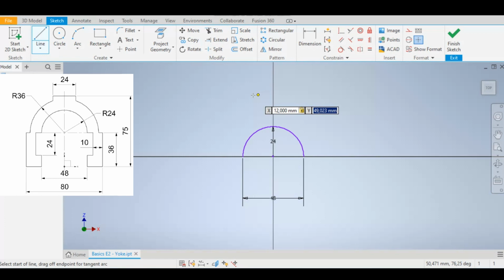So on the drawing we can see we've got a total length of 75 millimeters for our total sketch that we want to achieve, and our bottom section is 36. So I'm simply going to type in 75 minus 36, and there you'll see the preview. Once I've entered the tab option again, you'll see our Y value is 39 millimeters.